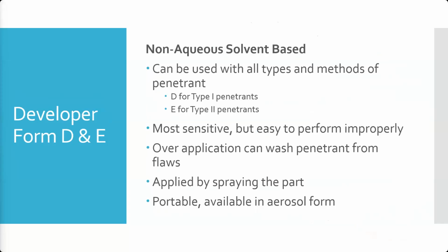We've gotten these, the stuff we got for portable. We have 2 penetrants. We have a fluorescent type 1, and we have a red visible dye type 2. And we specifically got those 2. We spec'd those 2 up because they actually use the same developer and they use the same cleaning solvent for both of them. So we really only need 4 cans instead of 6 different cans of stuff.